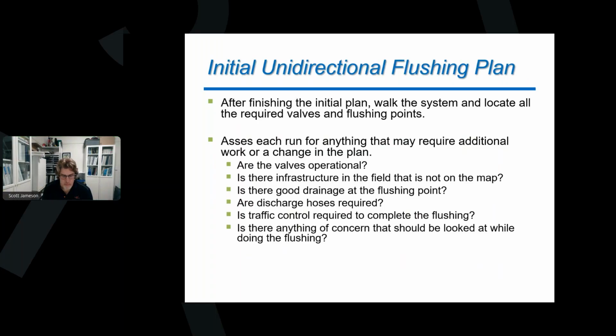So once again, go out, walk the system, locate all the valves, locate your flushing points, look at them with a critical eye, and try to see, is there something here that I need to adjust my plan for, right? Does this look like it's going to work for me?